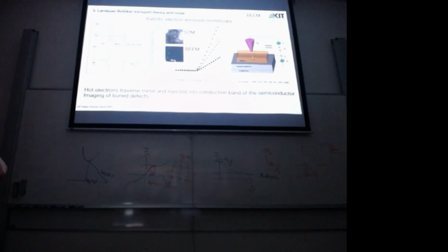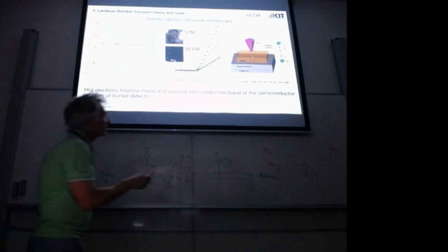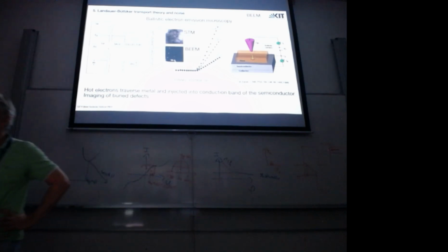Sorry, what is the role of the semiconductor in the right picture? It's an energy filter. If I have a small bias voltage, then they cannot go through the Schottky contact. So on this picture, this is the situation here. And if we increase the bias voltage above the band gap, part of the current actually goes through. I look at the left picture and I want to see on this picture the semiconductor itself. So this is the semiconductor. This is the collector current. The collector is actually behind the semiconductor.